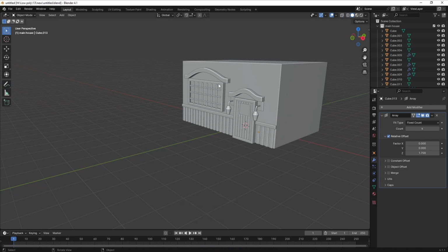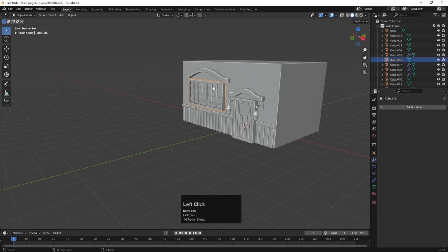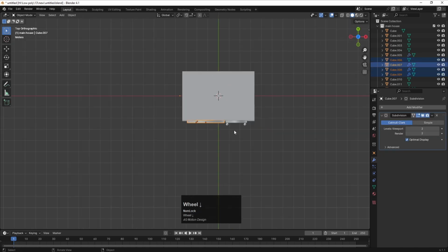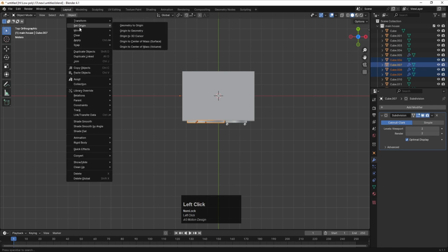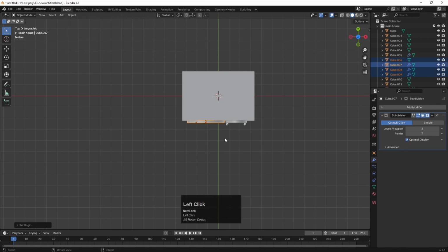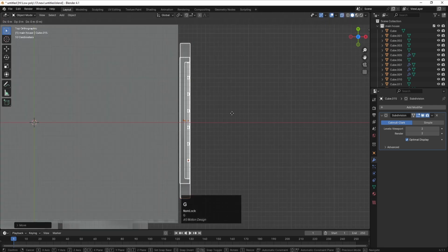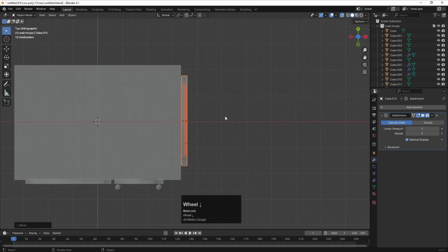So what I'm gonna do, I'm going to select this window, and I'm going to move this over here only. Okay, so for that, simply select this window, this portion, and this portion, and this portion. Go to the top view, press first of all, go to the object, set origin to the center of mass, shift D, and let's move this over here. Press R and minus 90 to rotate it on this axis, G, and simply bring this over here. You can go over here, Alt Z, G X, and try to adjust it properly, GY and try to adjust it over here.